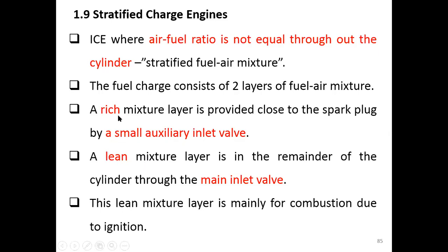Then we have another layer called the lean mixture. Lean mixture means an air-fuel ratio greater than 14.7. We provide the lean mixture in the remainder of the cylinder, the volume of the chamber that is not close to the spark plug, through another inlet valve called the main inlet valve.